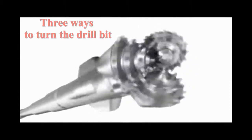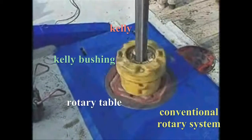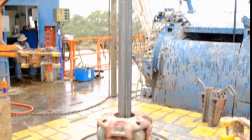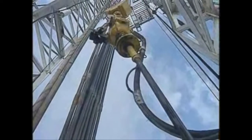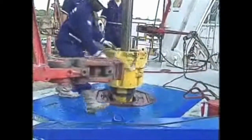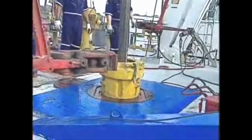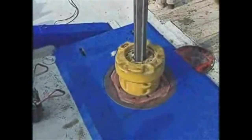The first is the conventional rotating system using the rotary table, the Kelly bushing and Kelly. The Kelly is a square or hexagonal shaped 40-foot length of pipe that threads into the drill pipe. A swivel connects the Kelly to the hook. The Kelly is fitted into a square or hexagonal opening in the Kelly bushing, which fits into the rotary table. As the rotary table moves, the Kelly and the Kelly bushing also rotate, thus turning the drill stem and bit below.